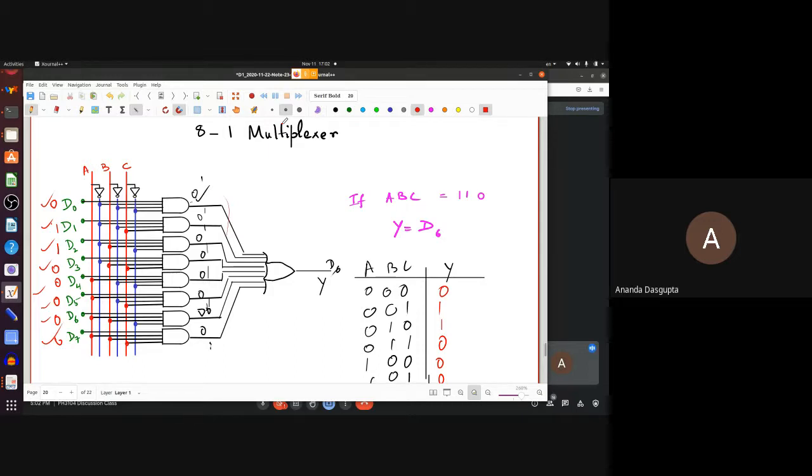So this is a circuit which is great for prototyping. For example, if you want to play around with different circuits and see whether what you really want to do is achieved by this particular circuit, you don't want to build a new circuit every time you want to play around with the circuits and change them. You can just use a single multiplexer. You can mimic all circuits with that. But for the sake of efficiency, once you're sure that this is the particular Boolean function you really want, you would usually go in for some other design. But this is very, very useful for many purposes, including as simple as this one, that you can make it work like any circuit you want. Okay. So are there any questions about this?